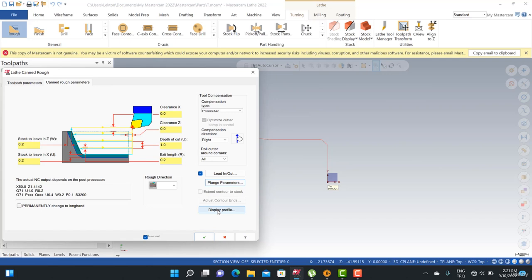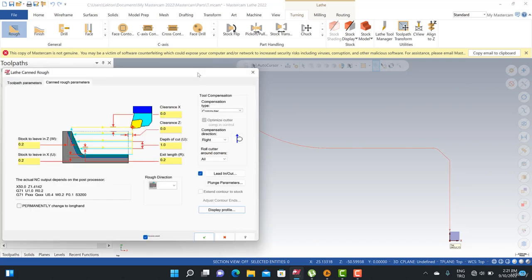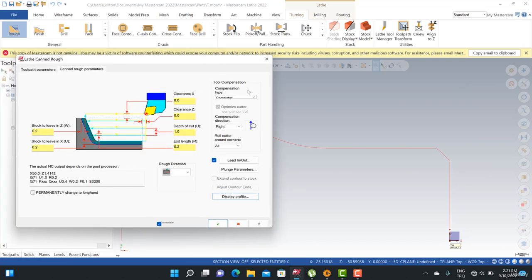Okay, when I click here, we can also see some geometry options. This is actually calculated according to my tool radius. So that profile is calculated automatically by Mastercam, because tool compensation is calculated by computer. We cannot see that because of my graphics card, but you can see that we can make them off. We can make them control.